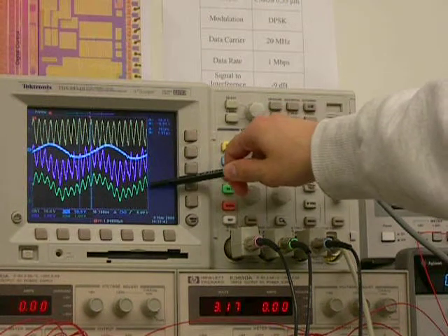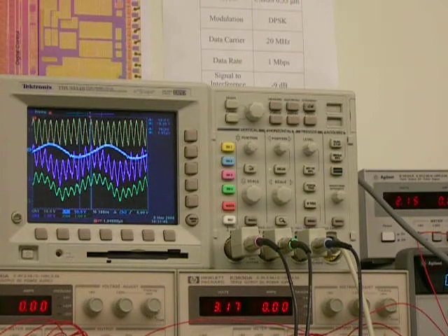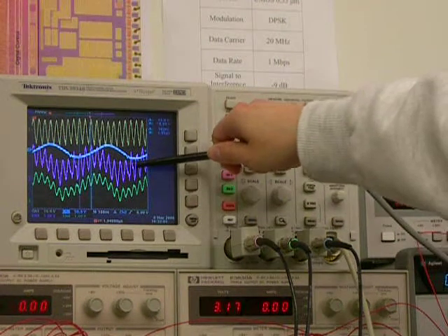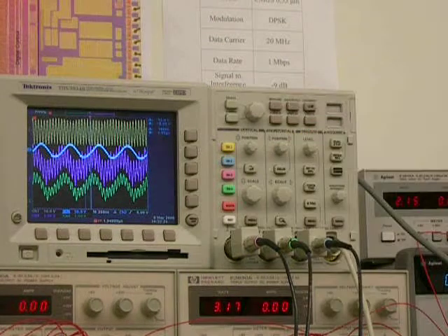The green trace underneath is actually the filtered version of the received data signal. In this prototype, we create a small, low-order filter to filter out the high-frequency noise received from the data coil. Now these high-frequency noises are generated from different places. Some comes from the power supply, some comes from the scope, some comes from the wires running embedded in the building structure. So now we have shown the intermediate signal.